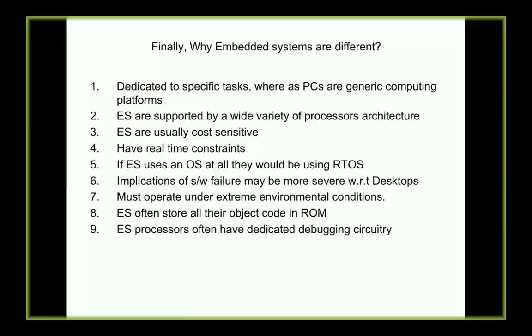Yeah, there's one of the biggest challenges. How do you transfer and talk from an embedded processor to a desktop machine? Because the desktop is the source where we will perform the development and download the application, correct? One of the easiest ways to understand this is that it has an OCD like JTAG or debugging circuitry, as we call it.